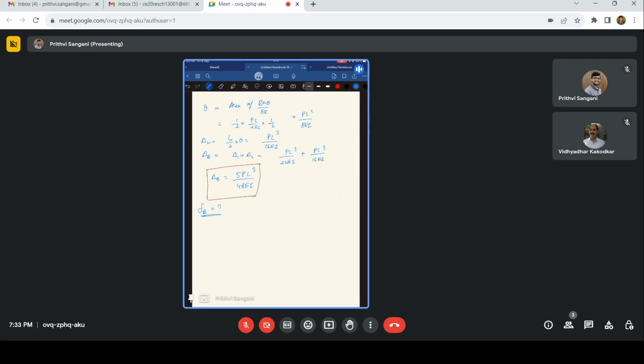This is 24 and 32. So 72 times 4.5, plus 24 times 3. This is going to be 396 kilonewton meter. So yes, this is going to be 396, acting in this direction, 396 kilonewton meter. Now what about the vertical reaction?